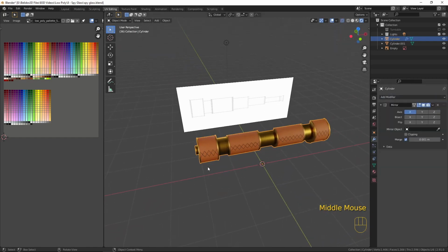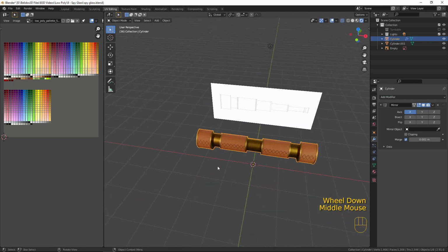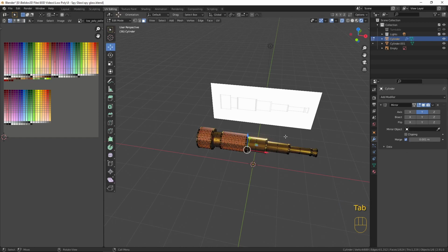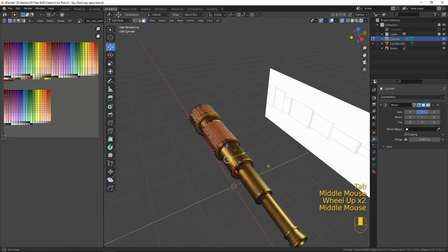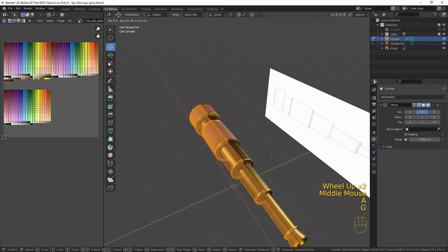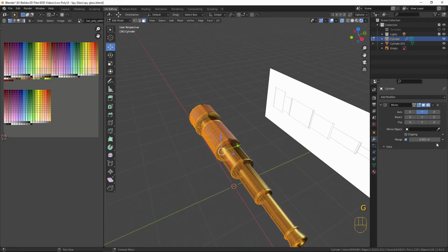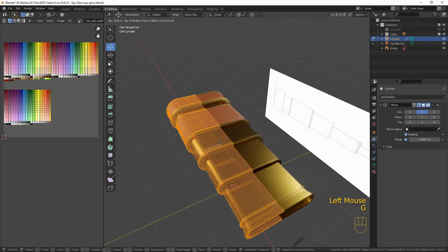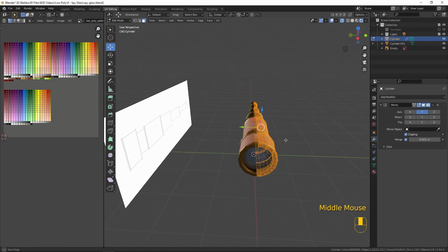And again, that's mirroring on the wrong axis, so I need to turn off the x-axis and turn on the y-axis. And always make sure you turn on clipping, and the reason for this is because at the moment, without clipping, I can do this. I can move it all apart. If I have clipping on, I can then move it and it stays in one piece.